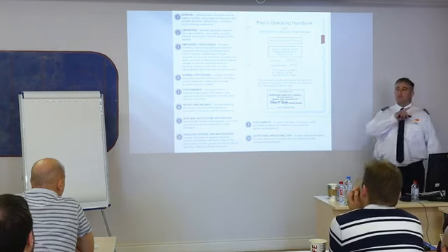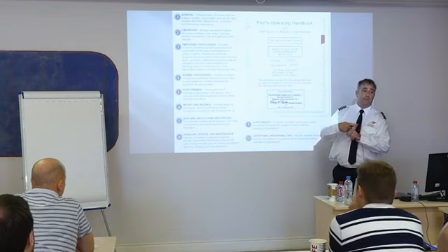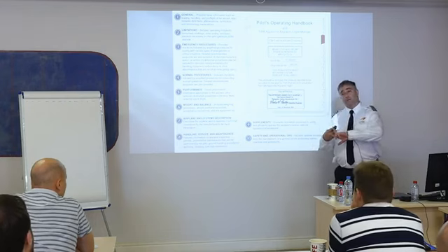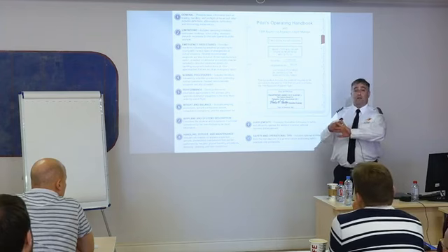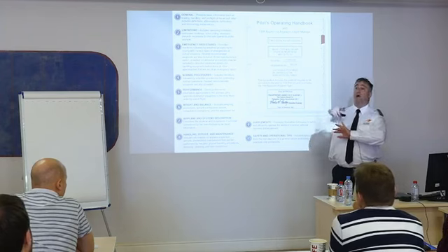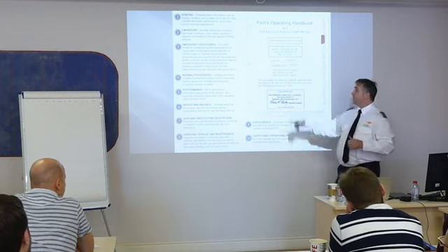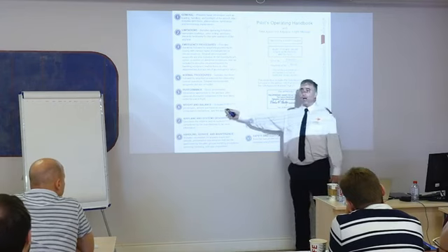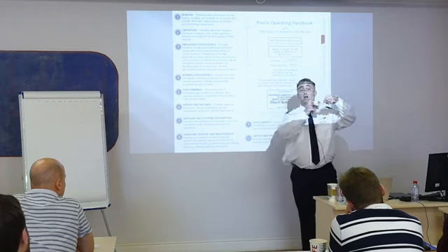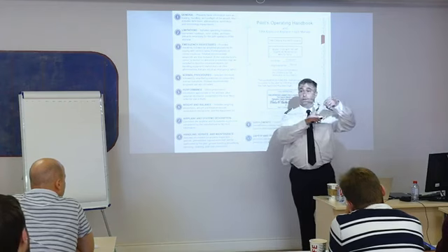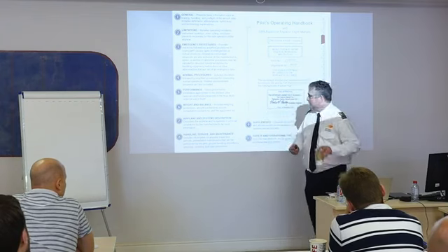Performance. Section 5 tells me this is how much distance it takes for the airplane to take off. How much it takes for it to land. Crosswind component that I might have. Fuel and time distance to climb. How much fuel am I going to consume on a normal cruise flight? Right? This is all your performance. Weight and balance. How do I know what the maximum weight is for the airplane and where I can distribute that weight? Right? To make sure that the airplane remains controllable. That's kind of an important thing.